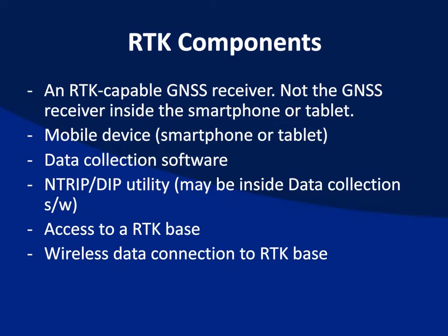Thirdly, you need some kind of data collection software, and that ends up being a really important question, a really important subject, and I'll talk about that further a little bit later. And you need some kind of NTRIP software utility. The purpose of this software is to manage the connection to the RTK base.